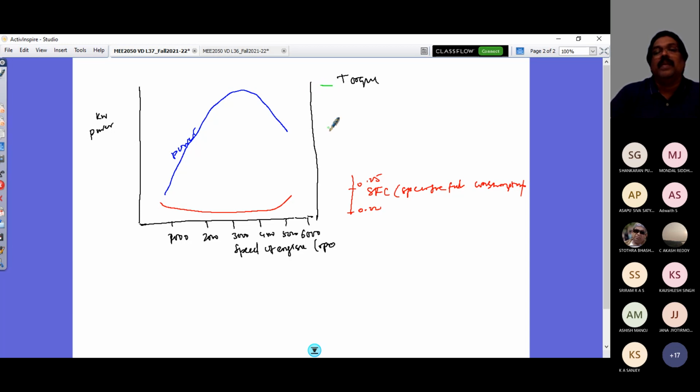And the torque variation, I will have the scale here. So the torque may be 160 Newton meter till 200 Newton meters. These values are for a typical vehicle engine that I look at. And the torque, if you look at the variation, is not like a hyperbolic variation that you have seen in the earlier plot. That would be varying something like this. It will be increasing and it will be falling so sharply like this. So this is the torque variation.